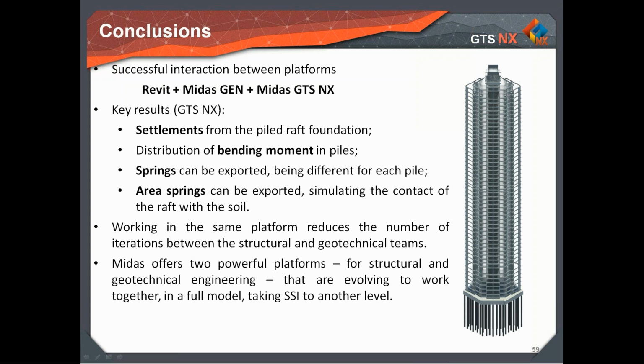As a final comment, we need to measure, which means that for every effort that we make to deal with complex models, we still need to match the real behavior of the structure. And in this particular case, every column of this building will be monitored for vertical displacement since the construction of the very first story, to make sure that we are heading in the right way.